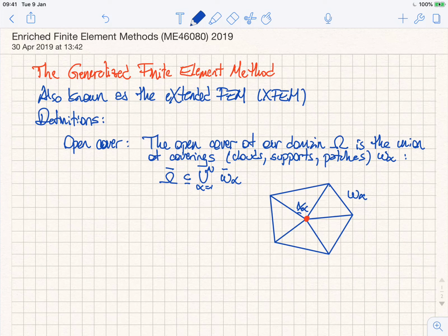And this has also important consequences in terms of solving, because how does our stiffness matrix remain? Sparse. And this is very important. We like sparse systems. We can solve sparse systems faster, okay? And they take less memory, so we keep also sparsity.